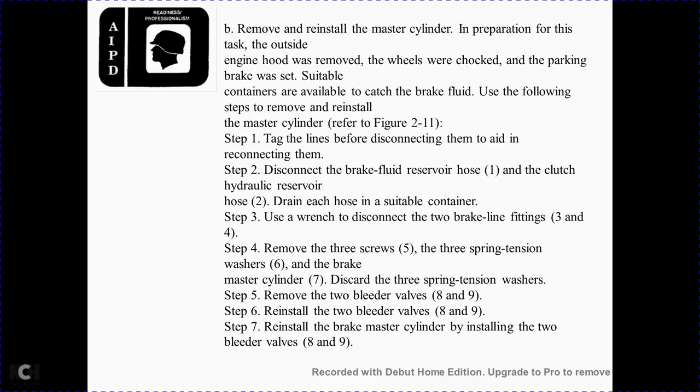the master cylinder. Remove and reinstall the master cylinder. Preparation for the task: outside of the engine hood, the wheels are removed with torque, the parking brake is set, and suitable containers are available to catch the brake fluid. Use the following steps to remove and reinstall the master cylinder. Refer to figure 211.